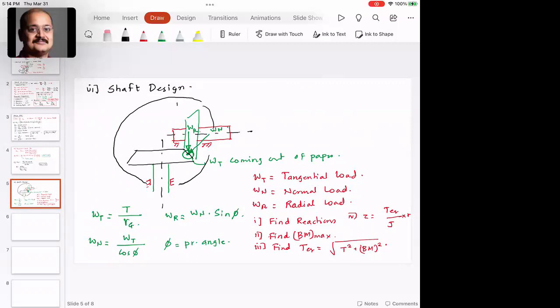Or this housing can be something like this as well. And then you can design the dimensions of the bearing and house the bearings, see if the bearing needs preload, and then add the seals, the covers, the gaskets, and make sure the gearbox is contained with proper lubricant, so that it would cool the gears, lubricate the gears, and increase the lifespan of the gears.